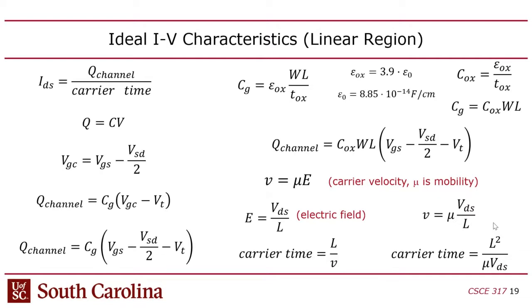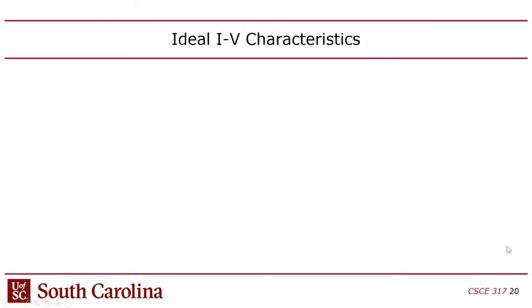Well, the reason there's such pressure on them is because of this, L squared. The channel length is wildly important for the performance of the transistors. So that's important. Intel's got to get the 14 nanometer process up and running, because look at how important this L term is.